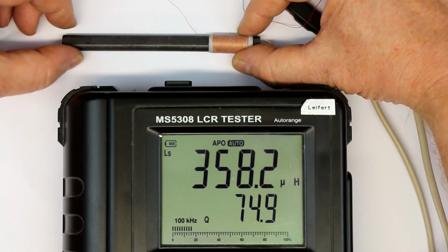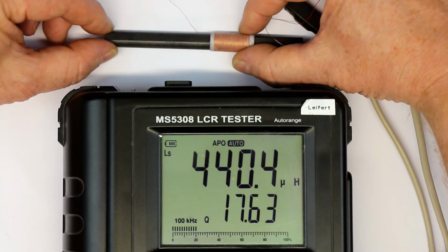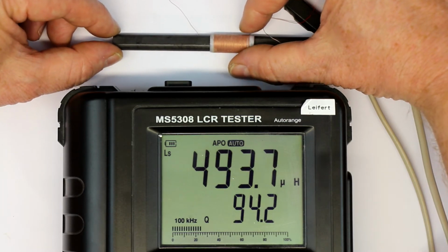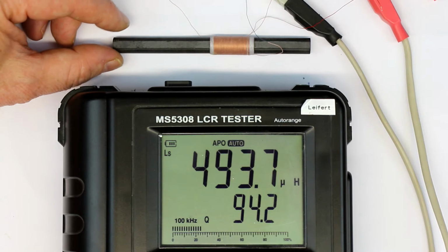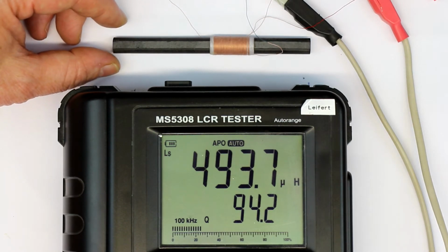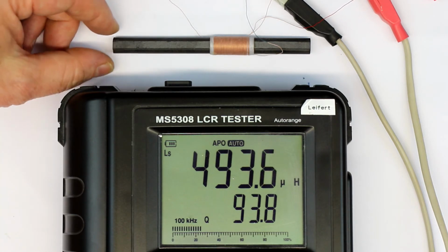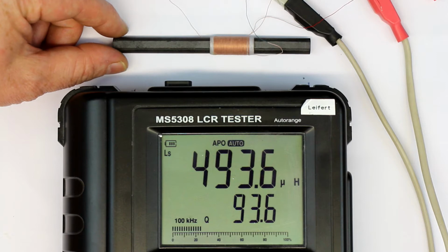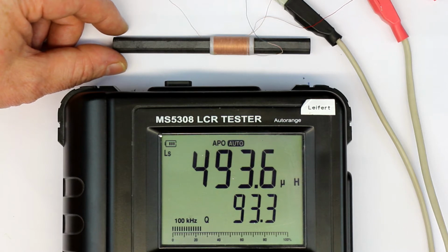So this is a well-known fact, and it's in fact used for fine-tuning the inductance of the coil, and that way the resonant frequency in an LC tank circuit at the beginning or at the end of your range. So that was the first thing, and now let's make a second experiment with our shortwave ferrite-rod antenna.